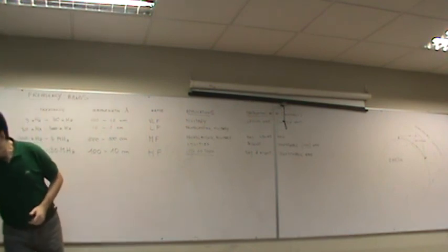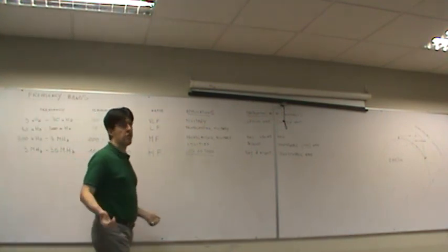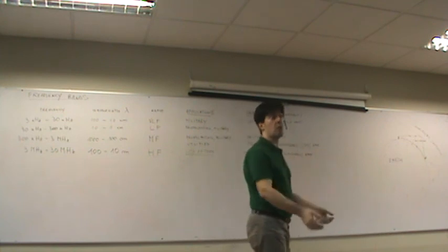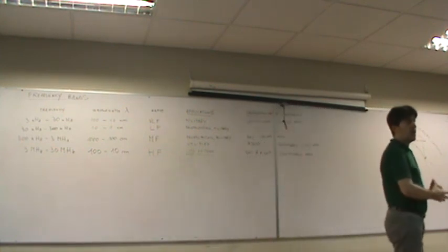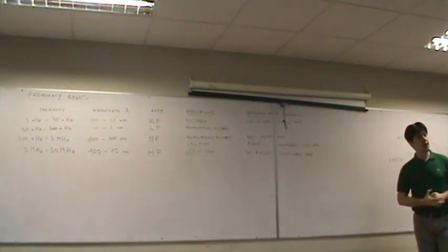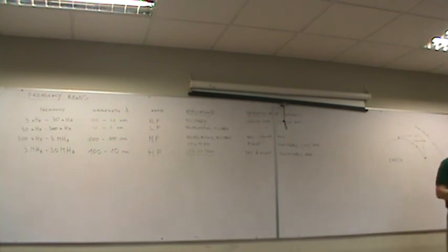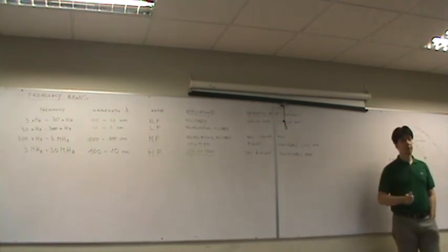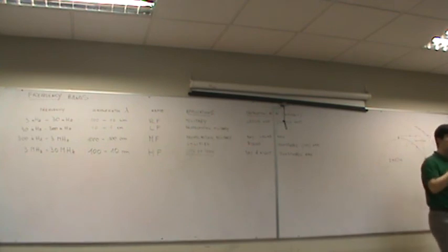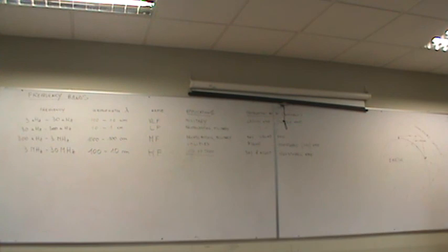This is the way the early long distance communication systems worked before the advent of satellite. But even today, those frequency bands are of interest. There are a lot of silent users on those bands, mainly military and civil protection, because it's the only frequency band that has global coverage without infrastructure.